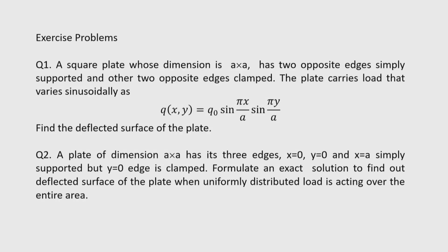So, now I want to show you how some other problem can be tackled with the help of this Levy's method. First problem: let us take a square plate whose dimension is a cross a and has two opposite edges simply supported and other two opposite edges clamped. The plate carries load that varies sinusoidally as q x y equal to q naught sin pi x by a into sin pi y by a. Our question is that the deflected surface has to be found out.